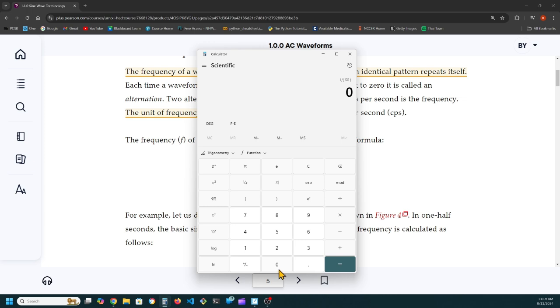If they tell you that a waveform is 0.01, let's say it's 10 milliseconds long for the entire waveform, you can just reciprocate 0.01. They say, how many cycles, how many hertz? Well, it's 100 hertz. It has 100 cycles per second. Okay. So just reciprocate the frequency.